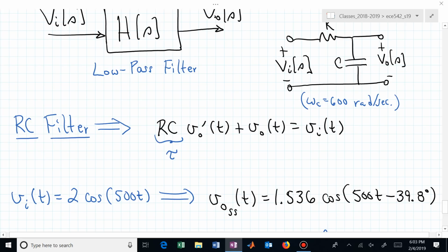And then you could start saying, well, I could find the DC gain of this filter and quickly sketch the Bode plot and say, how close is my actual frequency to the cutoff frequency? If it's quite far away, if it's much lower, then you can say, oh, approximately it's 2 for an amplitude. Here we're pretty close to the cutoff frequency, and at the cutoff frequency you're already 3 dB down. So you would be at 0.707 of your starting point, or 1.4 if you were right at the cutoff frequency of 600. So knowing that and seeing a 1.54, you go, okay, that makes sense.